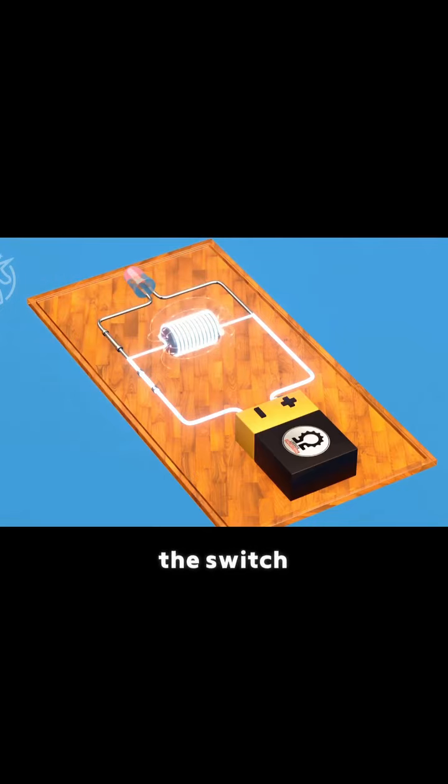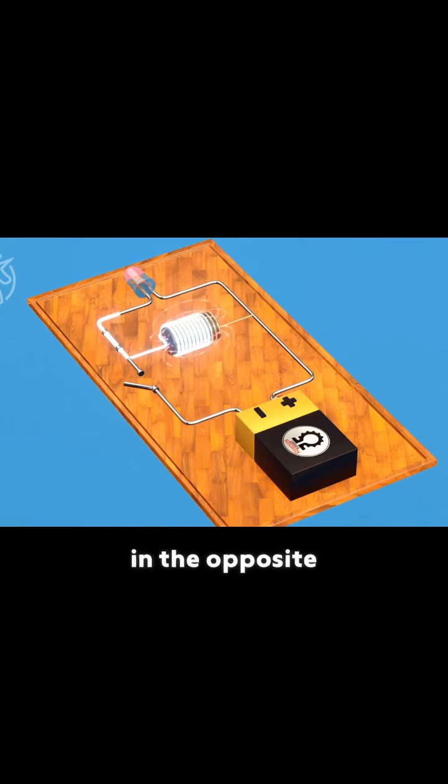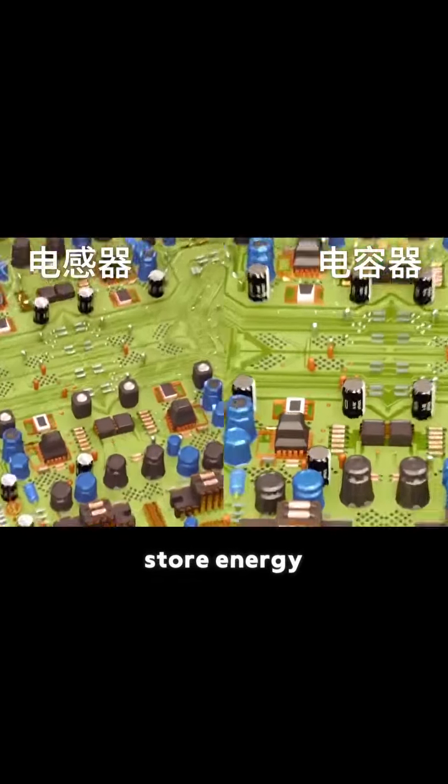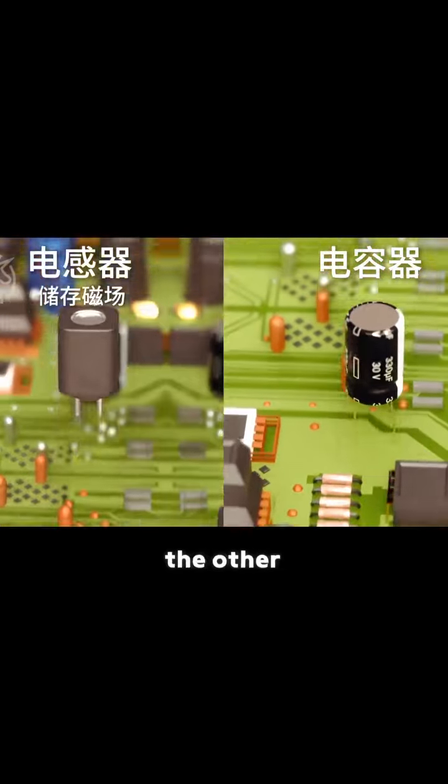Now when you cut the switch, the power stops, but the magnetic field in the inductor collapses, and as we mentioned earlier, a collapsing magnetic field induces current in the opposite direction, so the inductor releases that energy and keeps the bulb glowing briefly. So yes, both the capacitor and the inductor store energy, but one does it through an electric field, the other through a magnetic field.